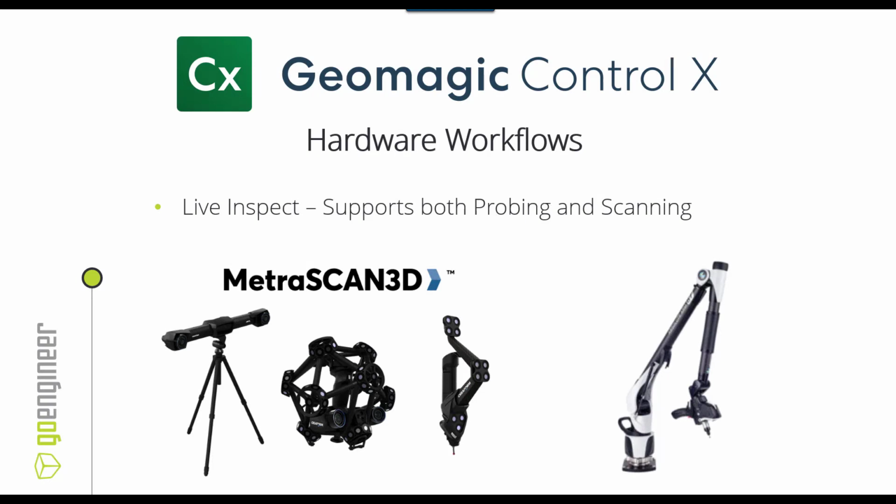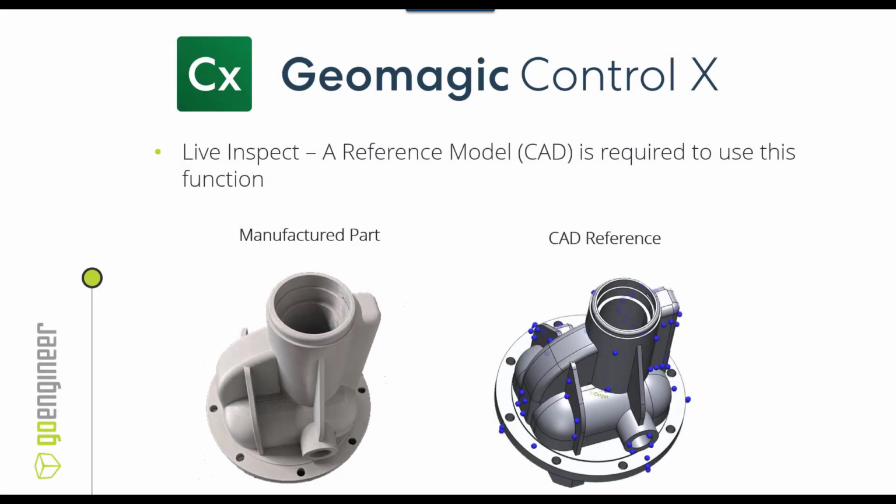With respect to hardware, Geomagic Control X supports both probing and scanning systems. On the left here, you can see a system from Creaform known as the MetroScan 3D system. In the middle, you have a handheld scanner, and you have a wireless probe on the right. Both of these devices are tracked with a dual camera system on the left. On the right, you have more of a traditional portable CMM. These arms can be probe only, or some arms have both probes and scanner capabilities. As mentioned previously, a reference or CAD model is required to use the Live Inspect function.